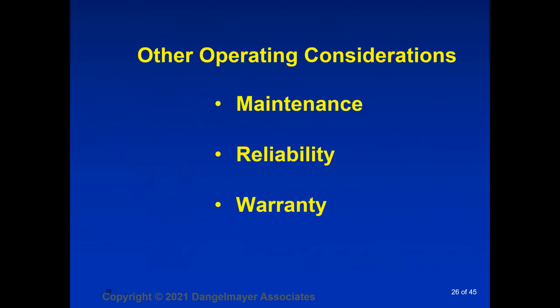So what are some of our other operating considerations? Well, first of all, maintenance. All ionizers need maintenance, period. I don't want to get into any distinctions here. All ionizers will require maintenance. The maintenance interval is determined by checking the ionizer periodically and determining when it needs to be maintained so that it doesn't go out of balance. There are no maintenance-free ionizers.